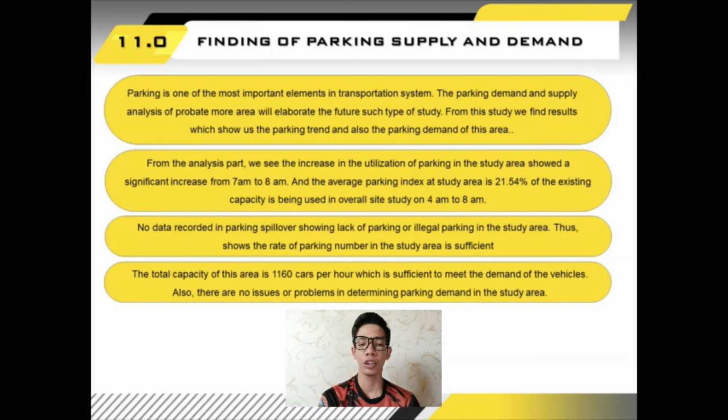In addition, no data recorded in parking spillover shows there is no lack of parking or illegal parking in the study area. Overall, the total capacity of this area is 1,160 cars per hour, which is sufficient to meet the demand of the vehicles. Also, there is no issue or problem in determining parking demand in the study area.